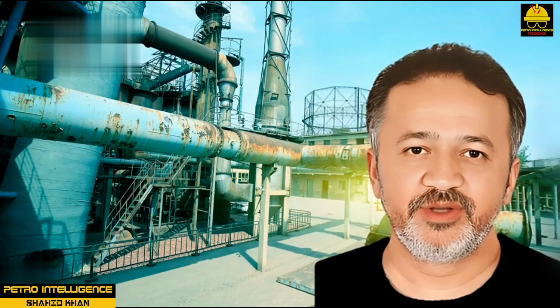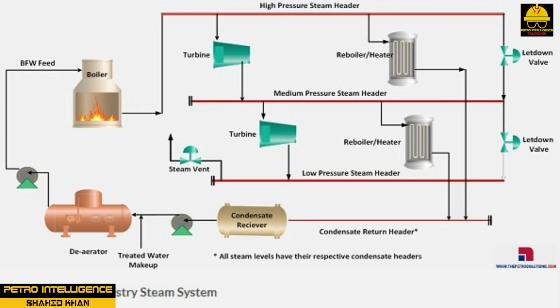Low pressure steam, 50 to 60 psig. LP steam is supplied by lowering the pressure from the MP header, or by extraction from a steam turbine continuous blowdown drum. Nominal steam pressure in the low pressure header is 50 psig. Steam to the LP steam header may be supplied from the exhaust of steam turbine driven pumps.